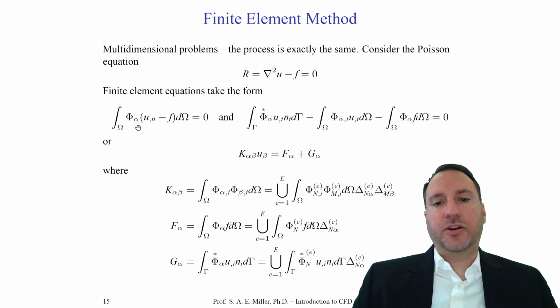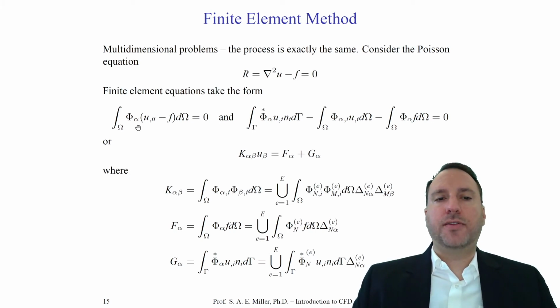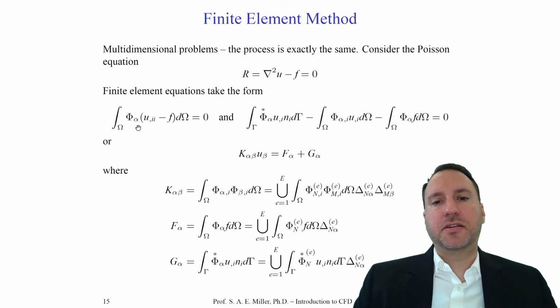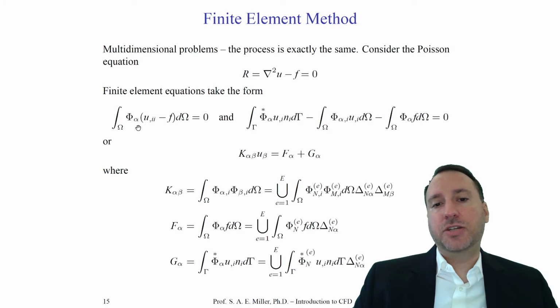In 2 dimensions for linear finite element solvers, which are working on triangular elements, we would have planes. And planes would satisfy all the conditions of the basis functions, which we showed earlier, but extended in 2 dimensions. In 3 dimensions and higher, you would of course have basis functions that are perhaps something a little more complicated, like tetrahedrals and higher order dimensional elements.